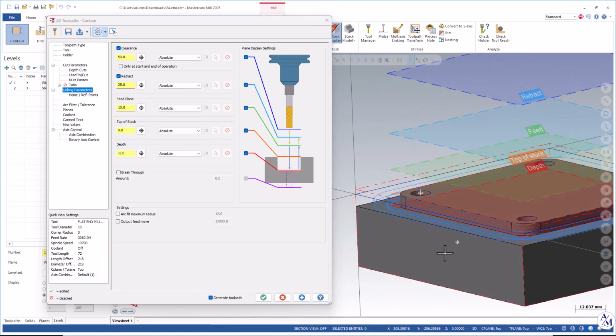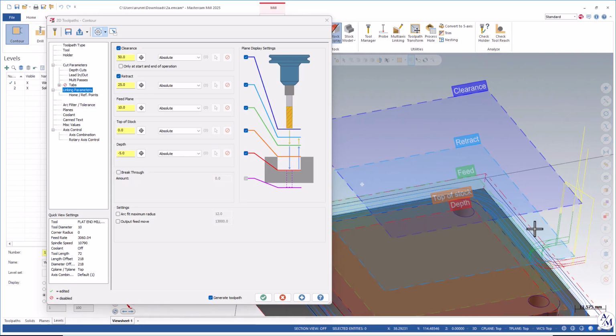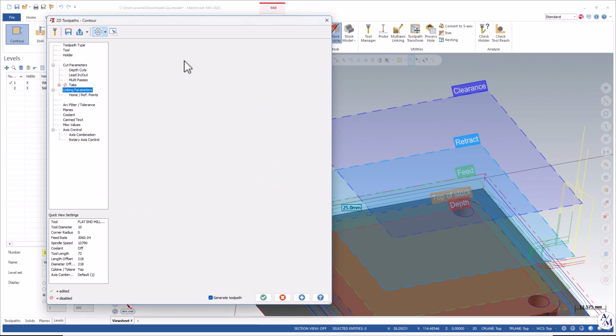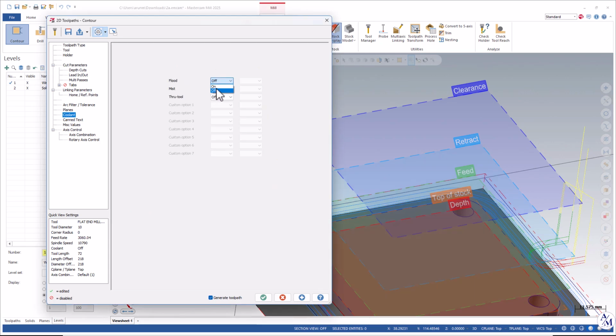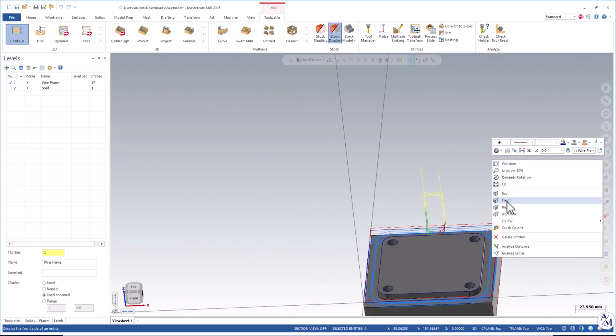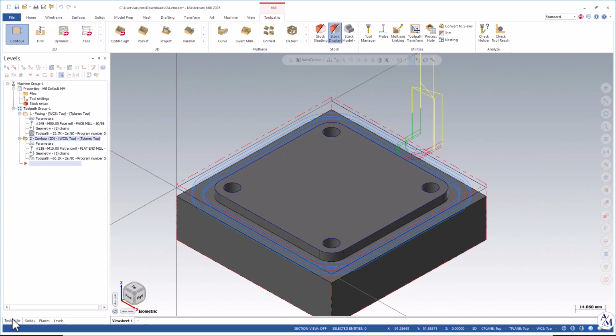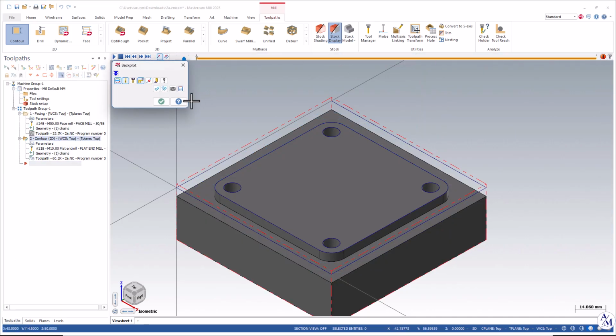So this is the latest toolpath. Here is the case I want to discuss with you. Let me first finish this off. Go to coolant, switch on the coolant, click OK. Now let me go for isometric view. You can see that this yellow color is representing the tool is always going back to the same position for each of the cut. Let me backplot it so you will understand.